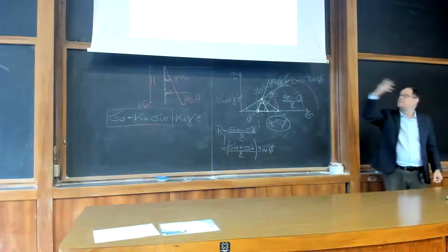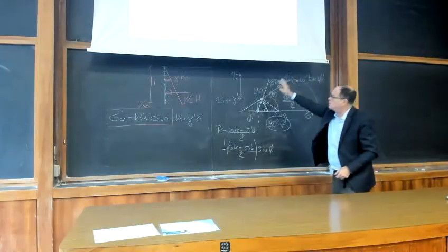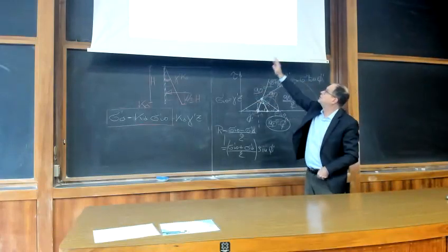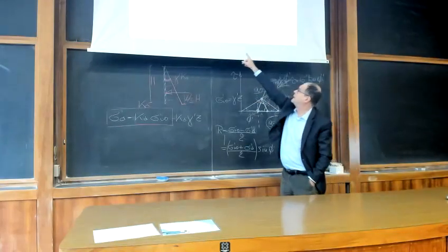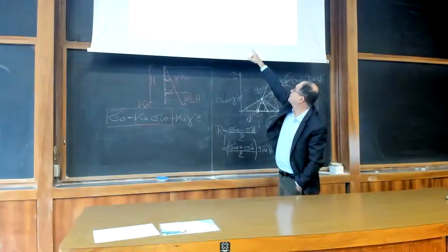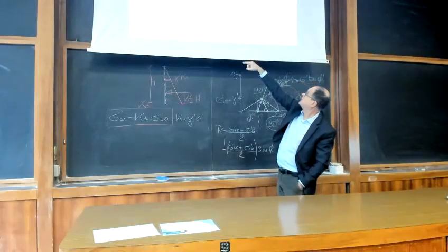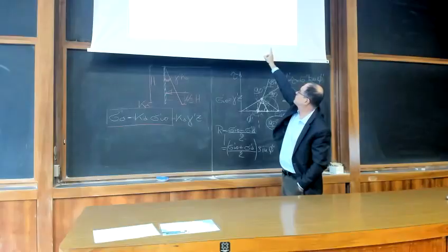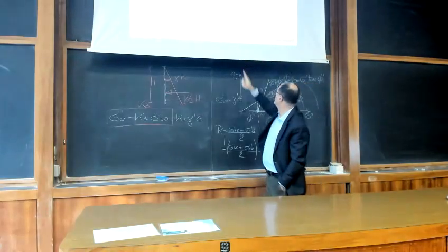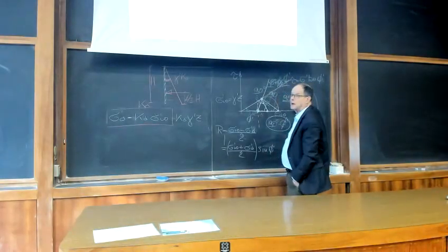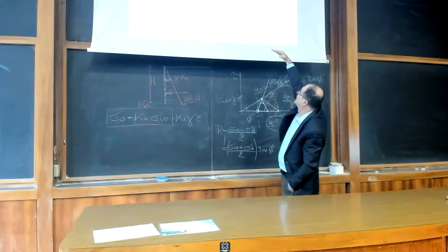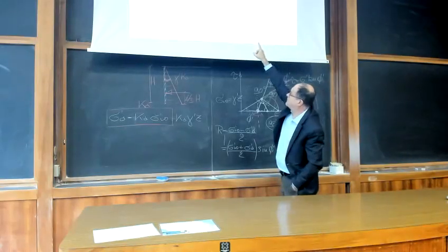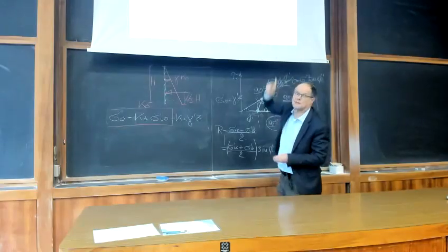This is the other circle. Now, I won't do it again on the blackboard. You have these slides, you have the other circle. The original planes move on the other side, because now the horizontal stress is the major principal stress, so the other angle is 45 degrees minus phi divided by 2, and so you have the slip planes inclined like that, and you have that Kp is that value.